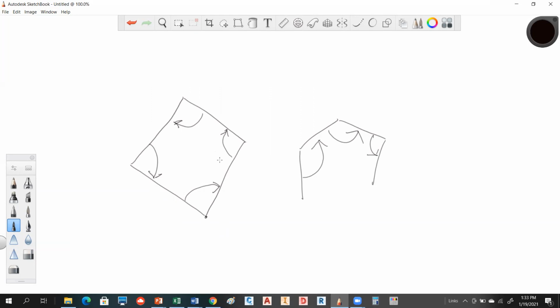But while I'm out there measuring, if I want to check this angle, I can measure that angle, and then I can measure this angle. If this is the interior angle and this is the exterior angle, the interior plus the exterior angle should theoretically equal exactly 360. So that's a good kind of check that some people use.